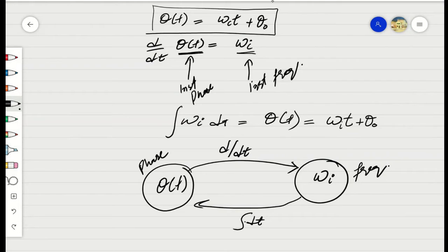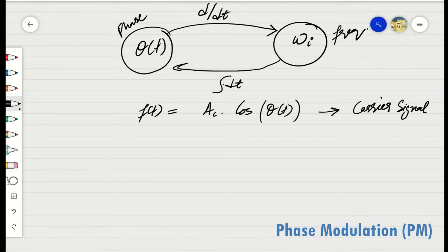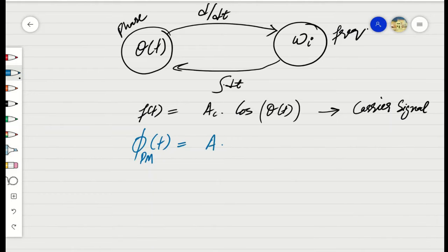This part represents the instantaneous phase of the carrier signal, while omega c represents the frequency of the carrier signal. So the first form of angle modulation schemes is the phase modulation scheme, where information is directly represented over the instantaneous phase of the carrier signal, starting by representing its time domain expression. In this type of angle modulation scheme, the instantaneous phase of the carrier is directly changed with respect to the amplitude of the information signal.